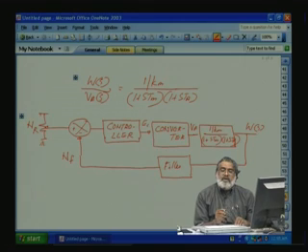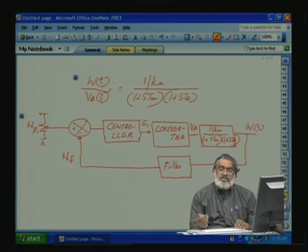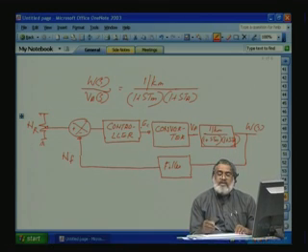So we want full control output, which for a 3-phase controlled rectifier is proportional to cos alpha. So cos alpha is equal to 1. So EC will go to the required value so that the converter should give the maximum voltage. So we will be applying the maximum voltage here. So let us take a case, a DC machine. We know the speed is proportional to armature voltage.